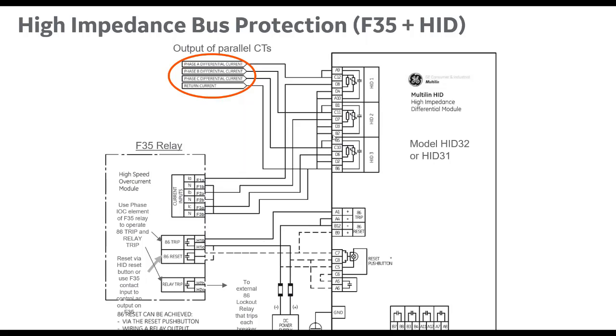And there's two ways of determining that resistor. You can have a variable resistor or you can have a fixed resistor. With the fixed resistor, and the HID module has a fixed resistor value, as John mentioned, with that fixed resistance, you can only have certain sensitivity levels, and that's what John mentioned. It could be up to 100 milliamps or lower than that. So there's a sensitivity range that resistor gives you.